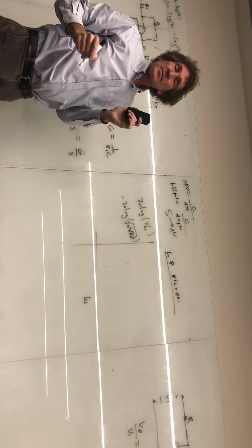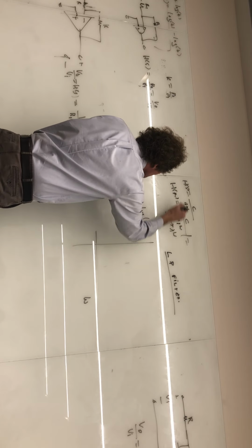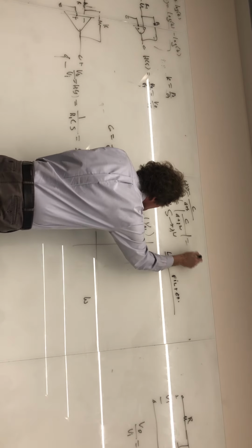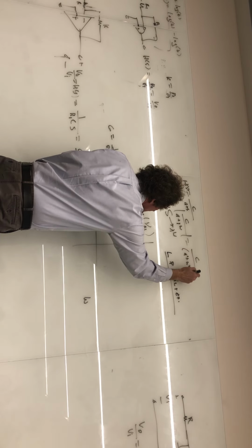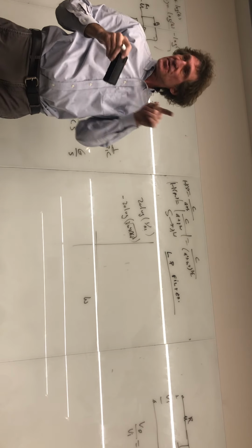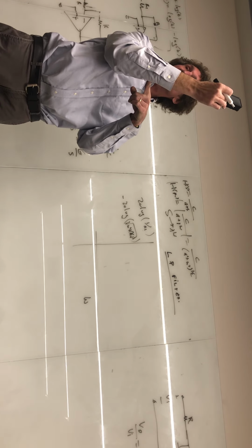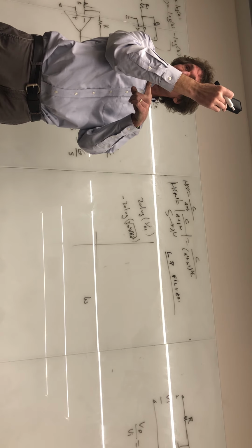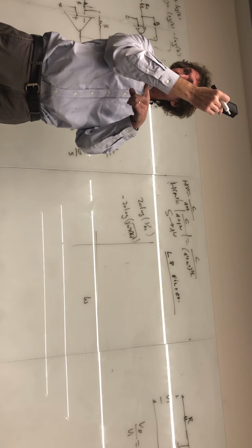Now I want the magnitude. To take the magnitude, that becomes c over the quantity a squared plus omega squared to the 1/2 power. Remember, the j omega and the a are not in the same direction. You don't square the j. You just take omega squared plus a squared in the square root. Do you all see that?